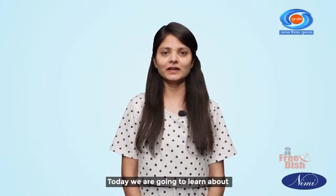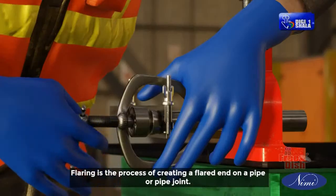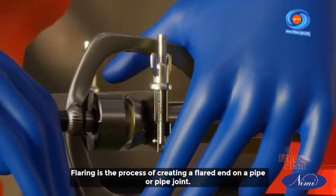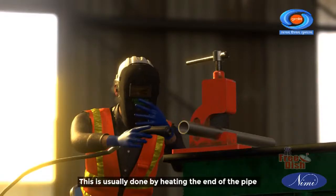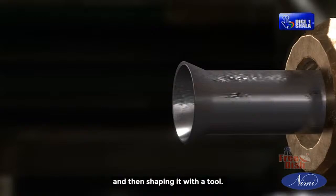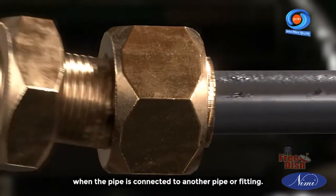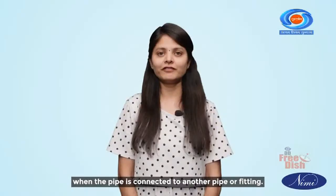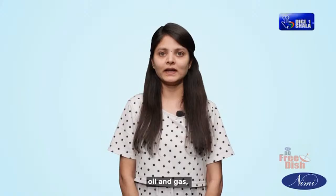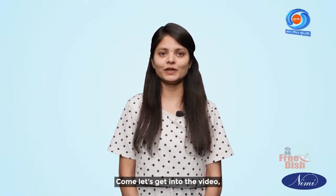Today we are going to learn about flaring of pipes and pipe joints. Flaring is the process of creating a flared end on a pipe or pipe joint. This is usually done by heating the end of the pipe and then shaping it with a tool. The flared end helps to create a seal when the pipe is connected to another pipe or fitting. Flaring is used in a variety of industries including plumbing, oil and gas, mining, and steam systems. Come, let's go into the video.